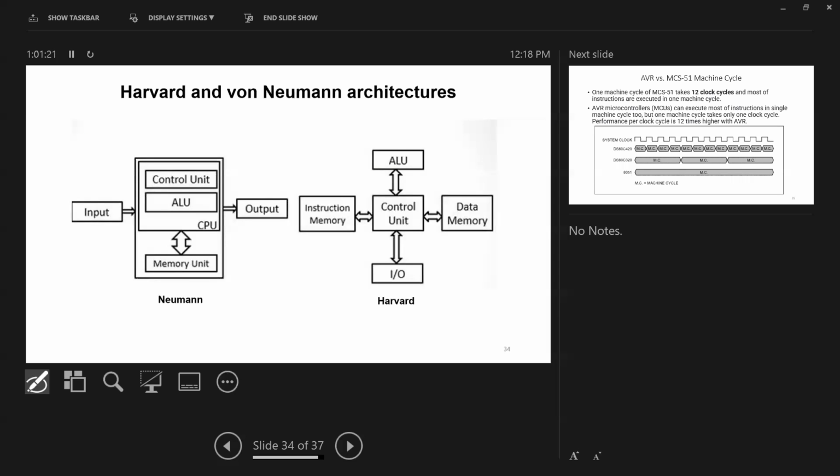Now, we could understand that in order to execute any instruction, we have many tasks. We have to fetch the data from memory, then decode this data to understand what would be the operation. Is it going to be a logic operation, arithmetic operation, moving data, whatever the type of coding, and then execute these instructions.